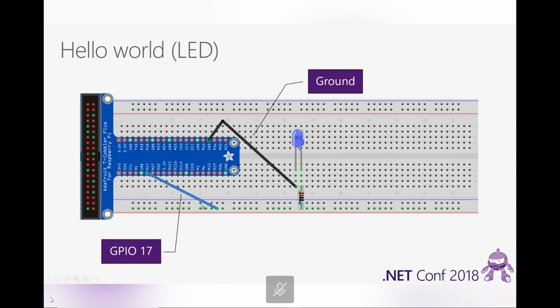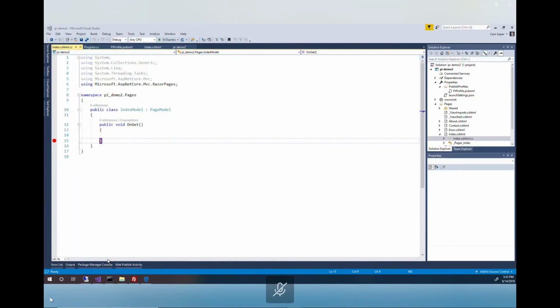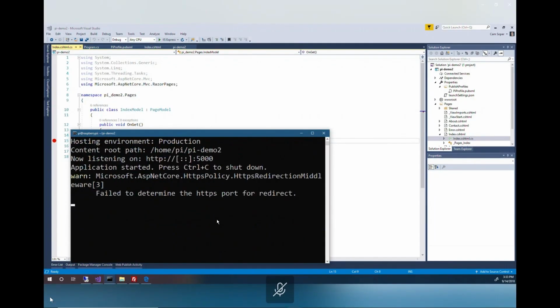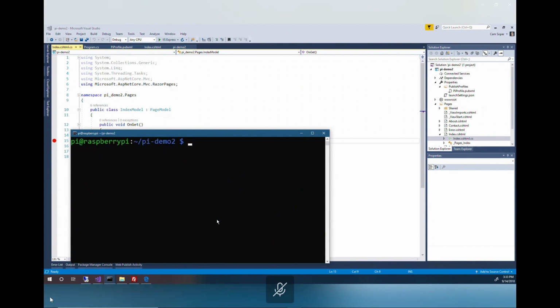So that's the circuit. Before I show you the code that's going to run this circuit, I need to show you a feature of the Raspbian operating system that's fundamental to how the code works. So let's drop out of the slide here, and I'm going to go back over to my shell. What I want to show you is a virtual file system location on the Raspbian operating system, /sys/class/gpio. This file system location allows us to control our GPIO pins directly through the shell. Let me demonstrate.